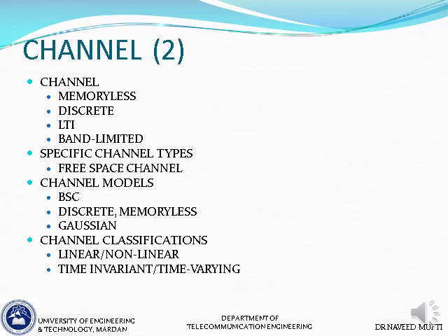और जो वायरलेस कम्युनिकेशन से रिलेटेड चैनल्स हैं उनको हम टाइम वेरिएंट अज्यूम करते हैं। फॉर एग्ज़ाम्पल मोबाइल रेडियो चैनल जो है वी क्लासीफाई इट एज अ टाइम वेरिएंट चैनल। इसी तरह बैंड लिमिटेड या पावर लिमिटेड, तो कुछ चैनल्स जो हैं वी कैटेगराइज देम अंडर बैंड लिमिटेड, जैसे टेलीफोन चैनल है वो बैंडविड्थ लिमिटेड है अप टू 4 किलोहर्ट्ज़, इट्स अ बैंड लिमिटेड चैनल। या फिर पावर लिमिटेड चैनल होते हैं, उस पर हम एक ख़ास पावर से ज़्यादा ट्रांसमिट नहीं कर सकते। सो फॉर एग्ज़ाम्पल सैटेलाइट चैनल्स दे फॉल अंडर द कैटेगरी ऑफ पावर लिमिटेड चैनल।